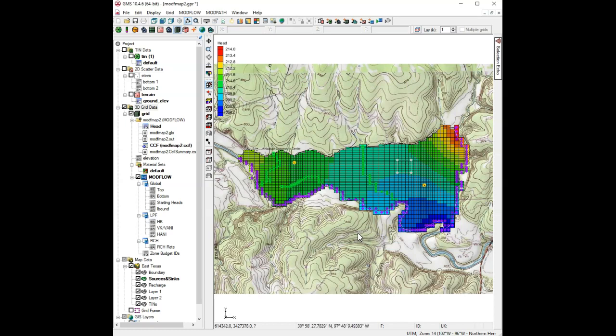You can use to define your porosity. So we're all set there. And so the next thing we're going to do, we're going to start generating path lines. And to do that, you generate what are called particles, or particle starting locations. These are hypothetical little particles that ModPath will then track either forward or backward in time, depending on the context, to generate your path lines.